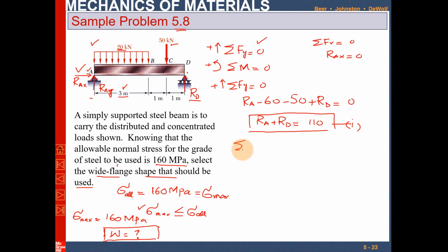Now the sum of all the moments, let's say about point D, is equal to 0, and counterclockwise is taken as positive. So you can say there is one force RA that is producing a clockwise rotation. Clear? So RA into the perpendicular distance from this point to this point, which is 5 meter, so into 5, but it will be negative.